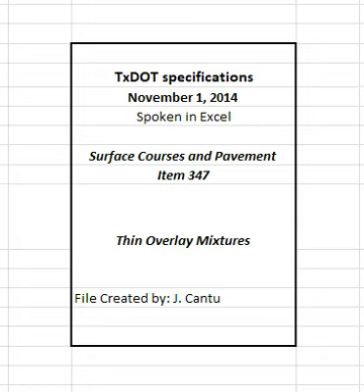4.9.5 Ride quality. Measure ride quality in accordance with Item 585, Ride Quality for Pavement Surfaces, unless otherwise shown on the plans. 5. Measurement. TOM will be measured by the ton of composite mixture. The composite mixture is defined as the asphalt, aggregate, and additives. The weights of asphalt and aggregate will be calculated based on the measured weight of TOM and the target percentage of asphalt and aggregate. Measure the weight on scales in accordance with Item 520, Weighing and Measuring Equipment.